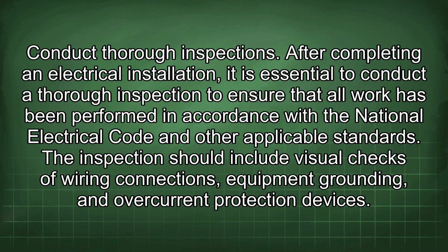Conduct thorough inspections. After completing an electrical installation, it is essential to conduct a thorough inspection to ensure that all work has been performed in accordance with the National Electrical Code and other applicable standards. The inspection should include visual checks of wiring connections, equipment grounding, and overcurrent protection devices.